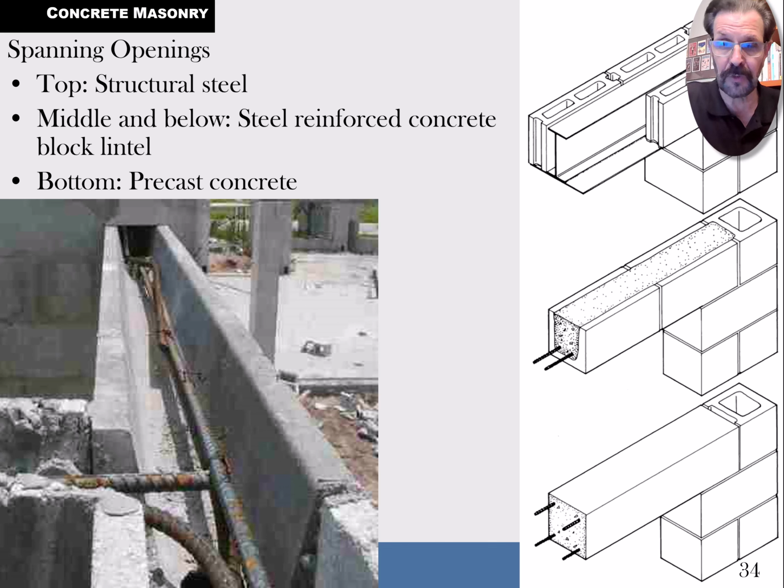You kind of see from here. They would, so that you can pour your concrete. And once the concrete is set up, then they can pull that temporary stuff out from underneath it. And in the very bottom picture, they've got a precast beam that's already been made, pre-made ahead of time, and they put that up and sit it over top.